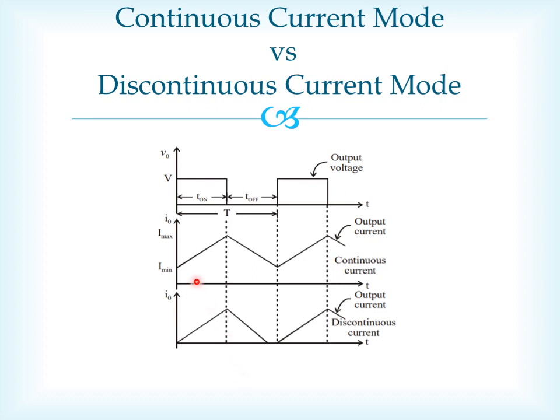So in a steady state we have to take this condition into mind that the current in the inductor is starting from some minimum value, and this minimum value is equal to the next minima again, and the maximum value is equal to the next maxima again, and so on. So it makes our derivation very simple, and it is easier to analyze the circuit under this condition.